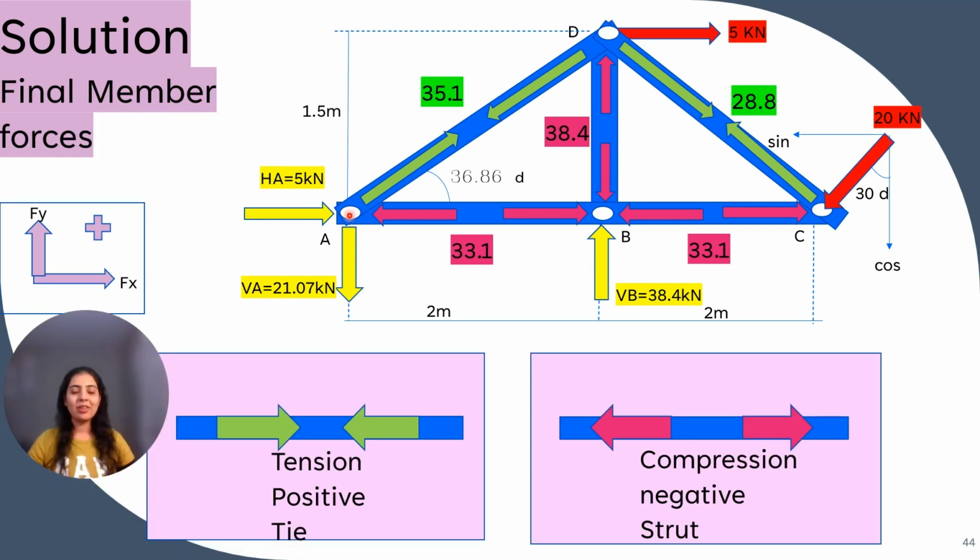So this is the solution of our truss problem. See the direction of support reactions with the sign convention if they are properly shown or not. Then check for member forces for the truss members. Are they according to sign convention or not? Tensile member force is positive and the direction of arrows is really important.